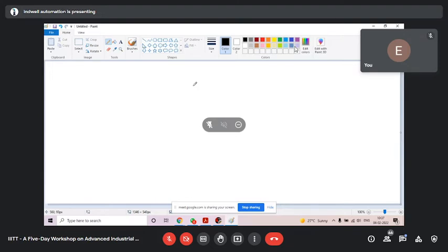And if you have to run your conveyor on low speed, suppose I want the speed of suppose 20 hertz or 25 hertz or 30 hertz, you don't need to run your motor on 50 hertz. You can run your motor now on 30 hertz only. Conveyor will run on 30 hertz. If you want to run your conveyor on 10 hertz, 25 hertz, 15 hertz, you can control the speed of motor, and you can save a lot energy and can save money also in your industry.